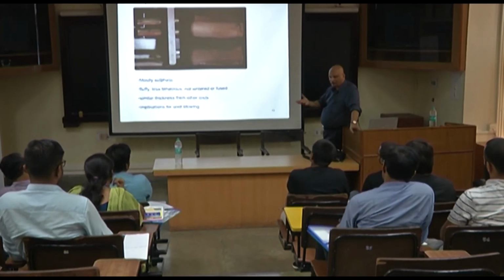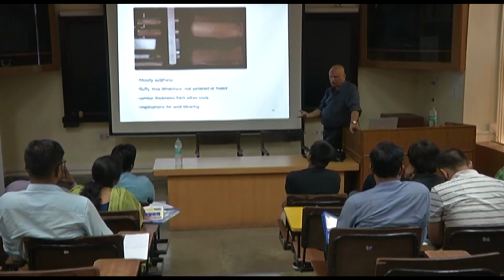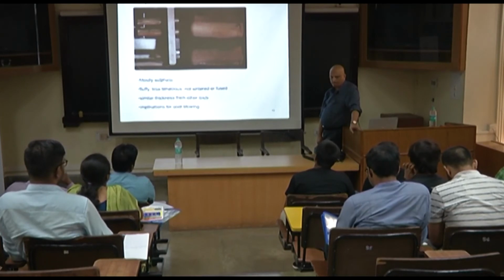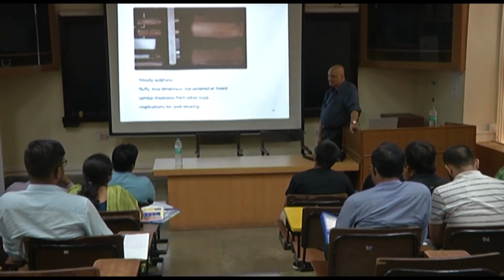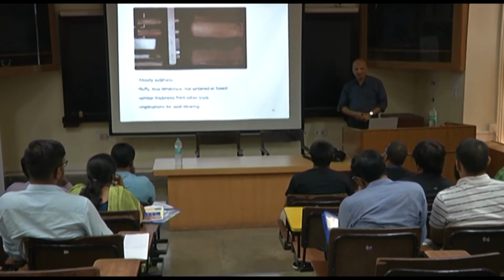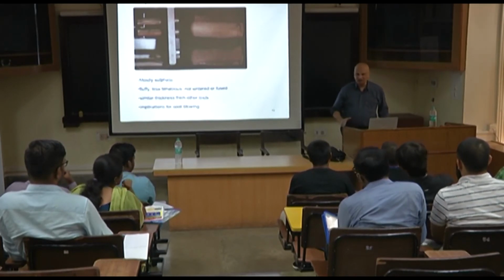Agglomerates forming, therefore pressure drop increasing, therefore the bed is slumping, fluidization will not be happening. So temperature indication and pressure indication are really the key, and therefore maintaining them is also extremely important.